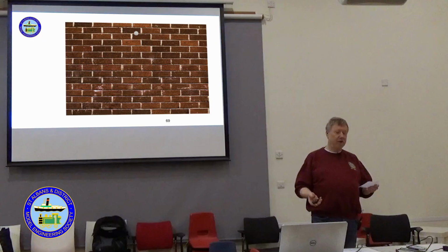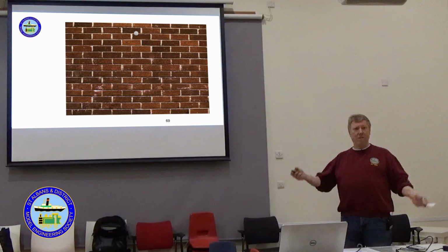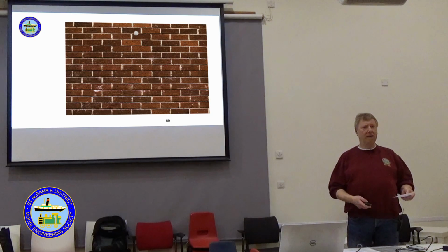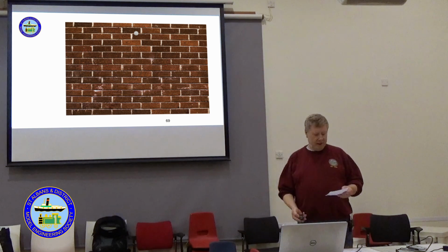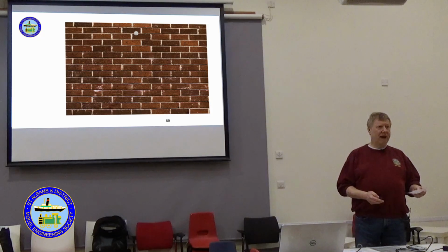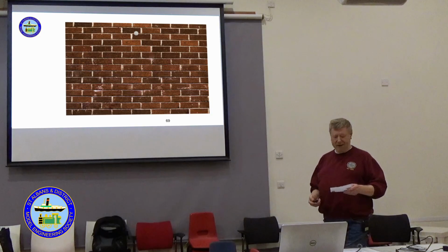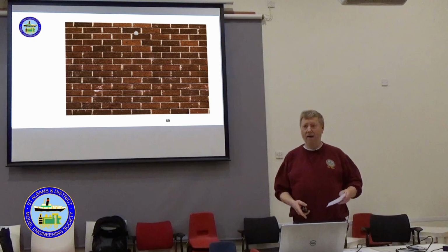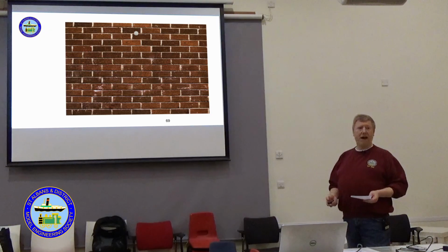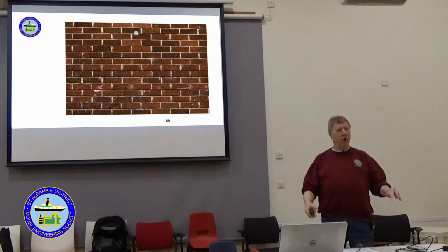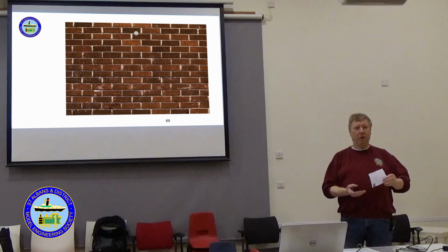So friction is obviously the most important thing on a railway, in two ways. The lack of friction in all the moving bits is the reason why railways are used to transport huge amounts of stuff around rather than lorries. But on the other hand, we rely on a lot of friction between the rail and the wheel, because if it didn't, it just slips. So we want as much friction as possible there and nowhere else. Now obviously in some of the steeper railways you might use cogs or stuff like that. On our normal railway we are purely talking about the adhesive action of a wheel squishing onto a rail.